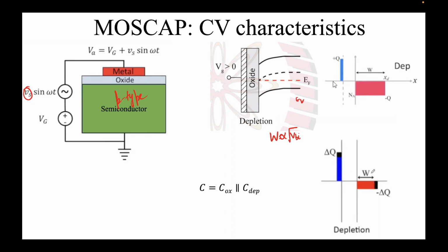So what I'm going to say is, this is metal, this is oxide, this is semiconductor. Where is the field dropping? Some field, which you saw in the last session also, correct? We saw potential dropping inside the oxide and potential dropping inside the semiconductor. So whatever charge is here, there are field lines that are emanating or ending from here.